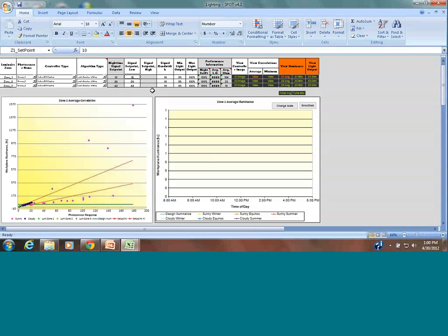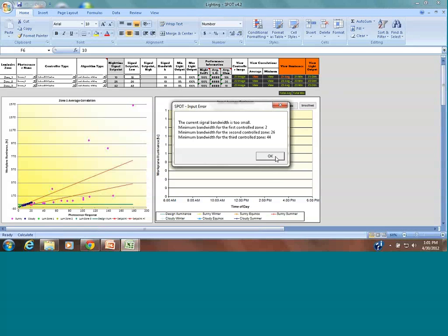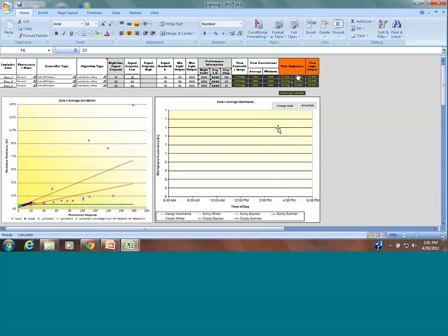This is probably where you need some help from your electrical designer in trying to help define this. I would again not have a lot of different zones and too many lighting sensors, photosensors. If you have one sensor, it typically doesn't give you as much problem. It automatically figures out the low set point for you. And I have to do some digging to find out how to fix this. But in general, it doesn't allow us to go further out because of that problem.